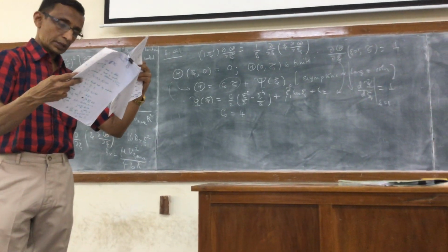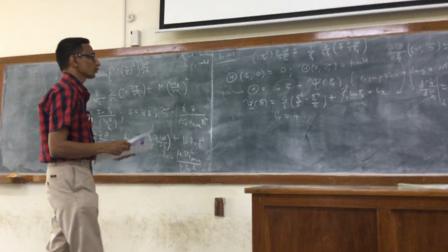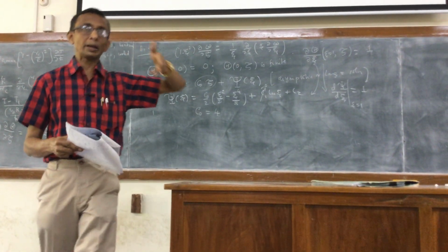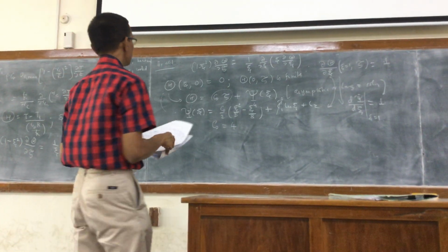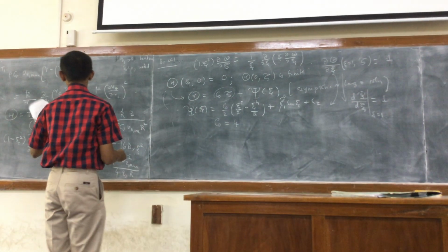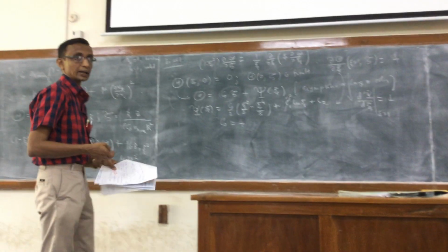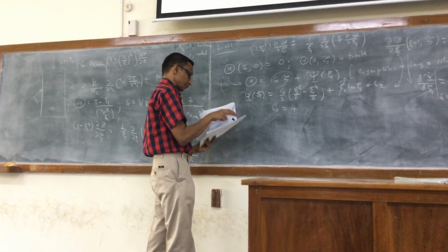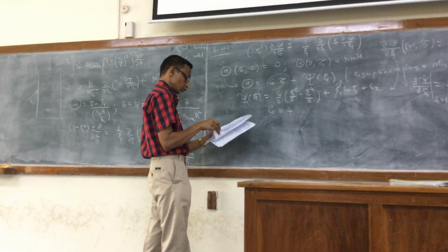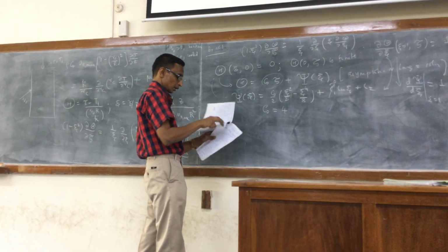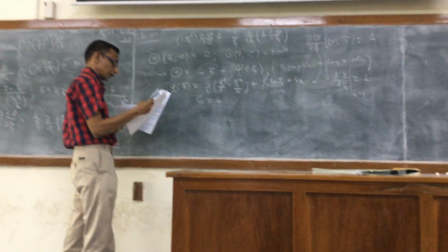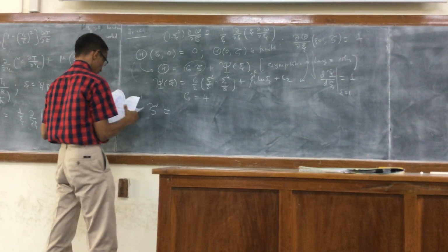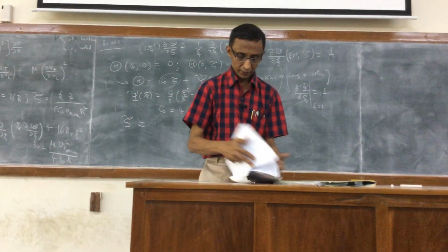Now for determining the constant C2, since I can't use this condition, what Boussinesq proposes is an integral balance over the cross-section, basically it amounts to integrating the energy balance, right? And then finally, and then neglecting the viscous dissipation term. And when we do that, the condition reduces to the following, namely that the integral balance leads to the following condition.